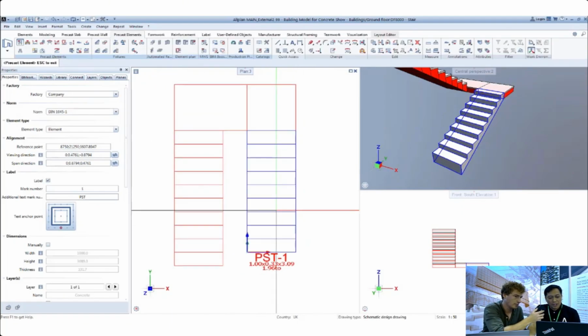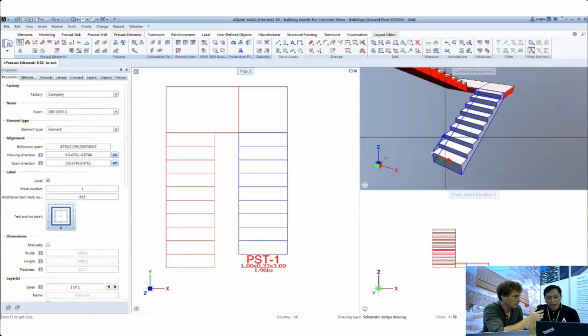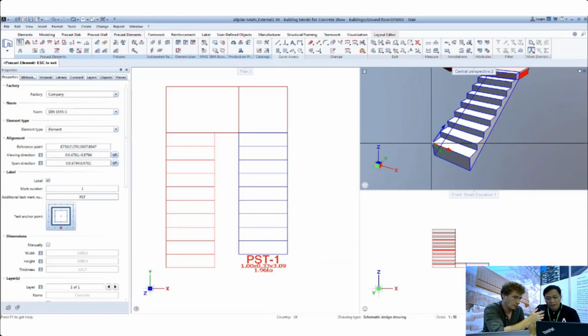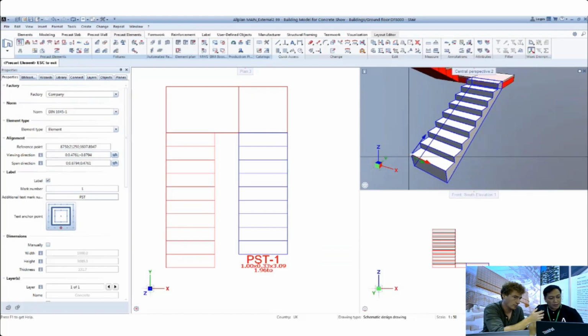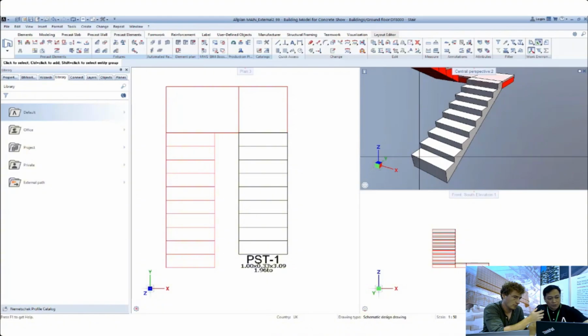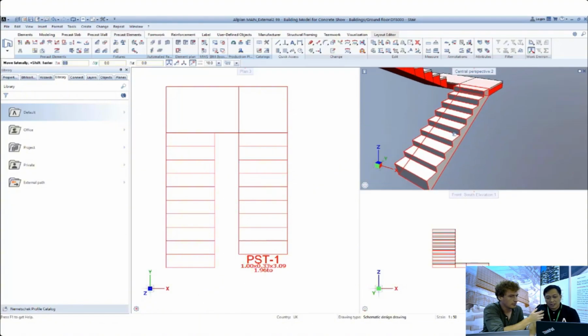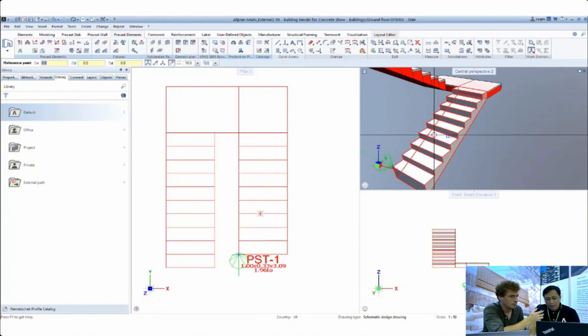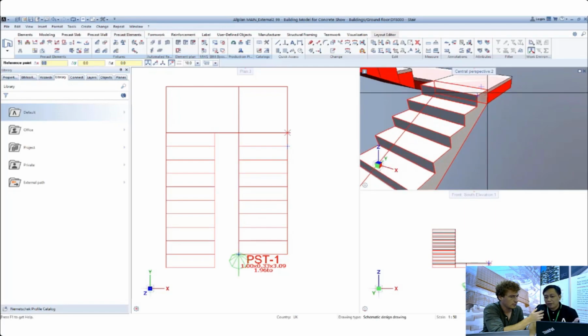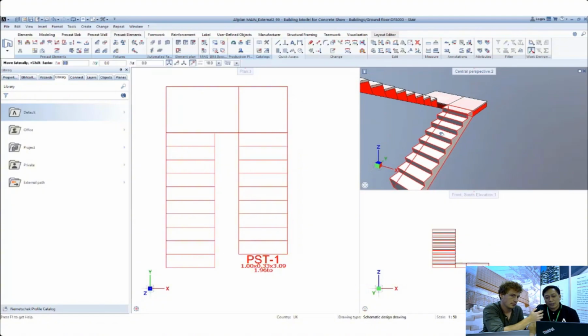For this case, as you can see, you have some directions here, wherein you can still modify, let's say, the point here. You can define this part by pressing escape just to terminate the command. Just select the element, and then from here, you point your cursor on a certain point, and then you can click on, say, modify reference point. From here, I can just click, and let's say I want to put it somewhere here.